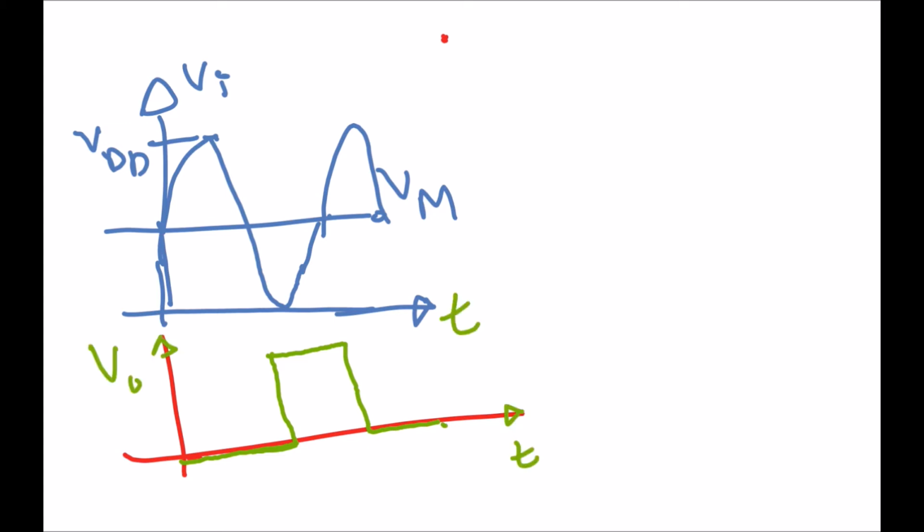What's different for a Schmitt trigger? The Schmitt trigger is used to differentiate between V input high and V input low. Here, let's put some ground rules. We here talk about an inverted output Schmitt trigger, which means that it is an inverter with hysteresis.